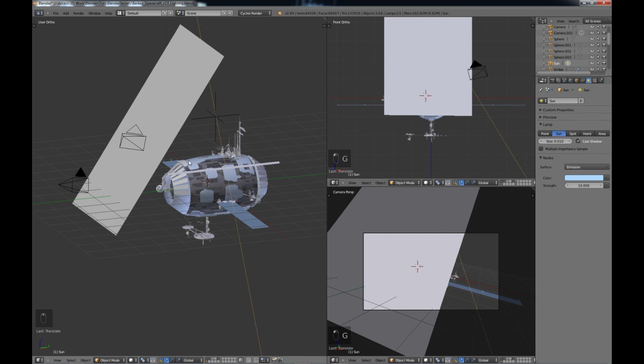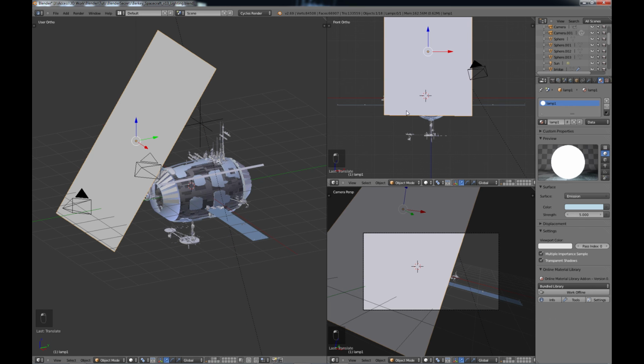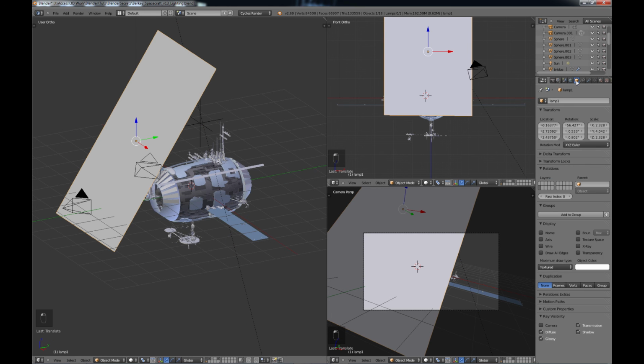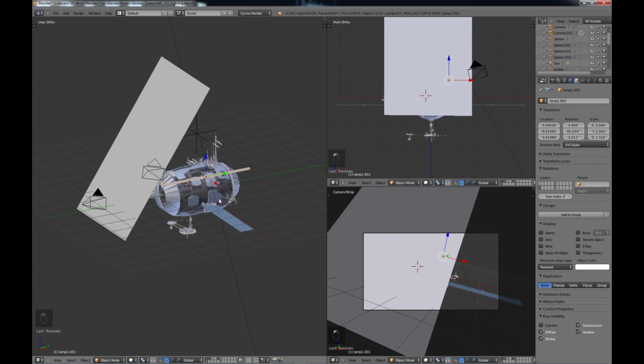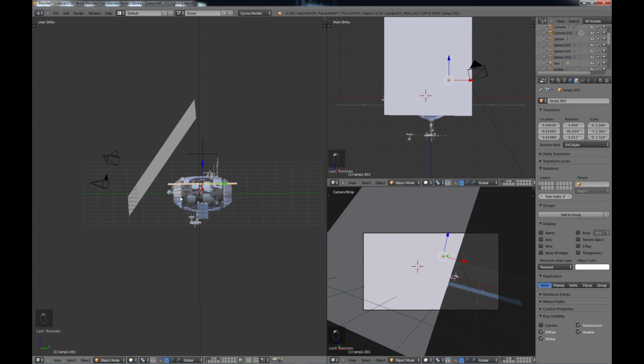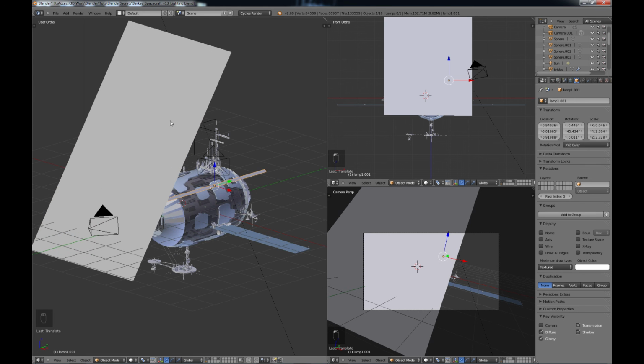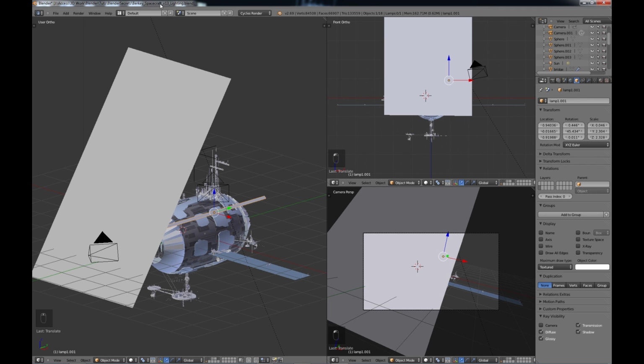The other thing, of course, like we did before, we want to choose our lamps, go into the object data here, and just make sure the camera's turned off, so if it's in the way, then the camera won't see the panel at all. Same thing for this one, we have the camera turned off, and that should be good. And also I had saved this as version 13, of course, for the lighting. So I'm just going to do a quick save. That is it for the lighting.